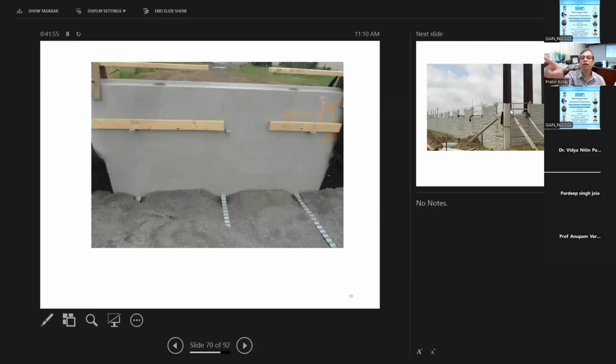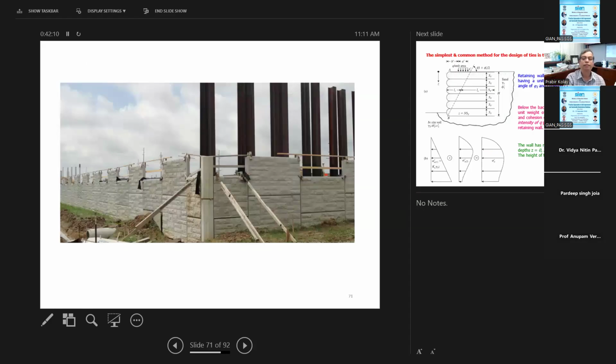So this is the concrete block already. So you can see now this is the horizontal spacing. From here to here is the vertical spacing. And then also the concrete facing wall can be anything. From the outside, it looks like this. This is very common these days, everywhere in the world now. So it's MSE wall design. So you can really construct a vertical wall. Okay.